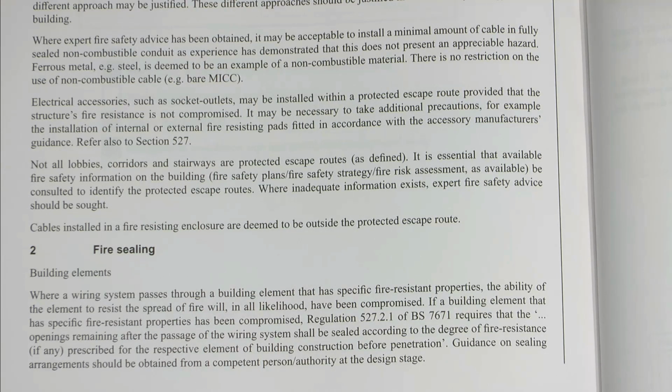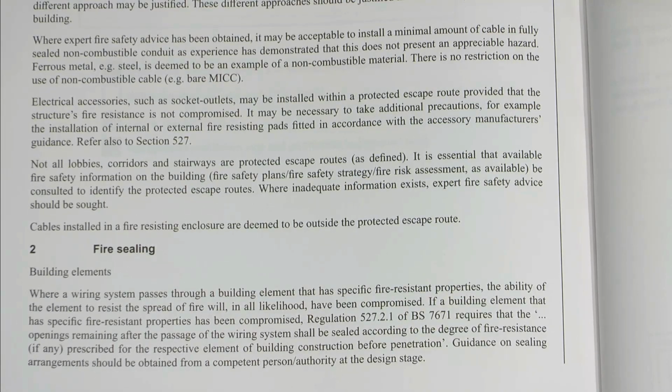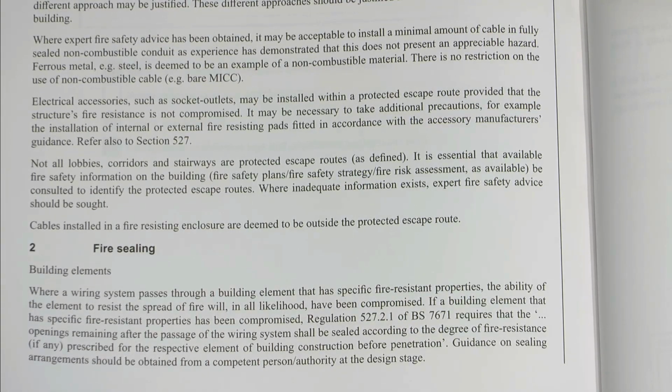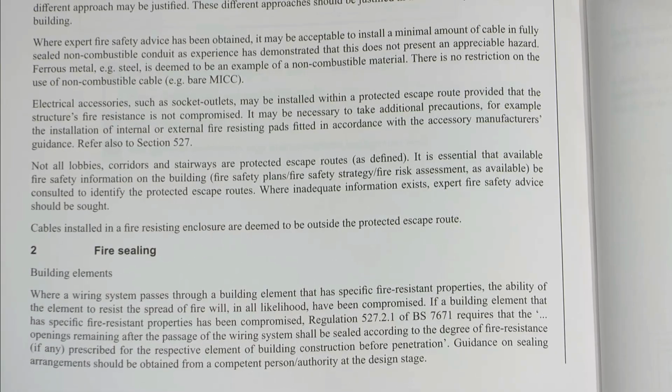So if you're going to go to, say, a large block of flats and start installing cables and things, or even pipes or anything else for that matter, then before you even start the work, it should have been designed in how you're going to be making holes, where they're going to be put, what you're going to be doing with them afterwards, and what method you're going to use to seal them, and the types of materials and all of the other stuff. Certainly not a case of going in there just randomly drilling holes and then saying, oh well, there's some holes now, because of course if a fire occurs, fire and smoke can go through those holes and spread to other parts of the building far more rapidly than was intended, which leads to all kinds of problems.